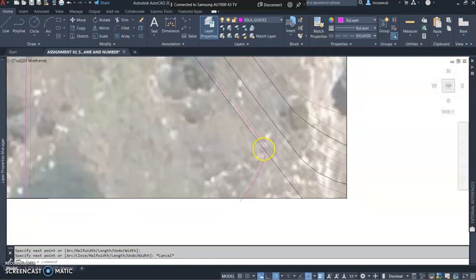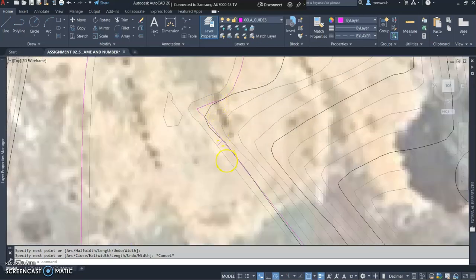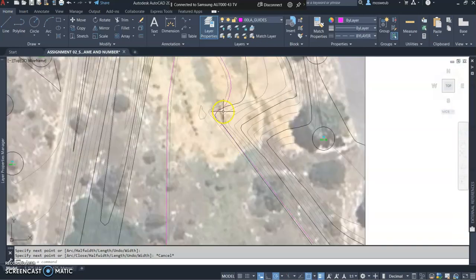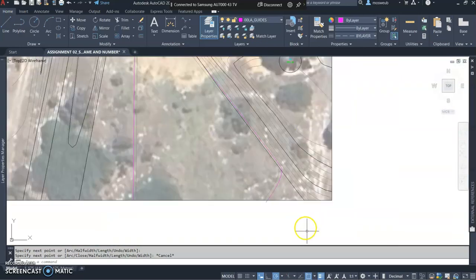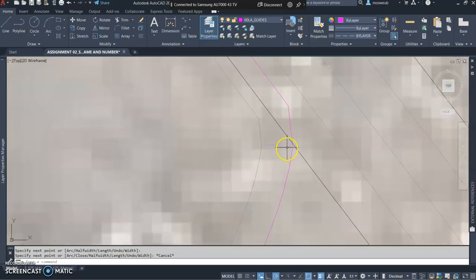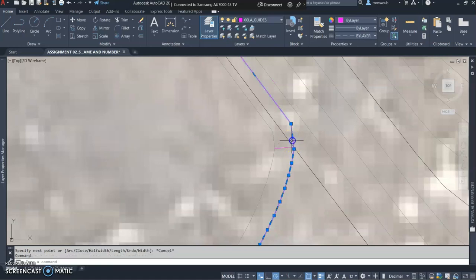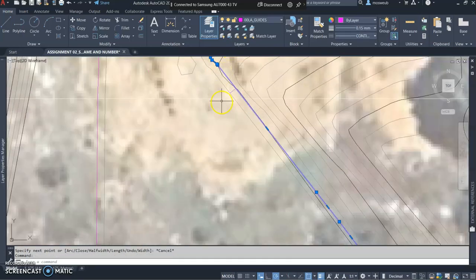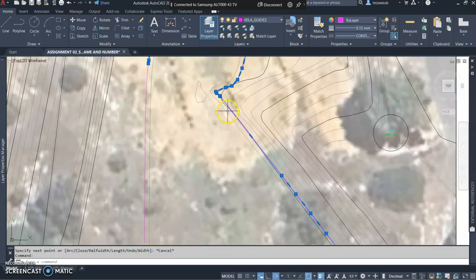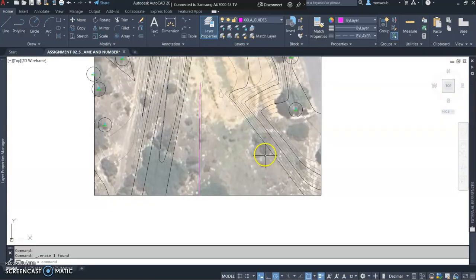Everywhere there's an intersection with the next layer at 800, find those points. Okay, there's another one there, so you can just click on that point and then connect to the original layer at a perpendicular angle. Then once you've connected all those points, you can just delete the guide line,